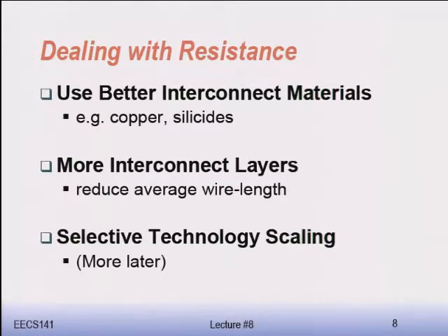Okay. I think also we will see that not only is the introduction of copper important, but we also increase the number of interconnect layers, and that is to make routing easier, okay? To give more degrees of freedom, and you make wires shorter. We'll talk about this in a little bit. These things will become a little clearer, okay?